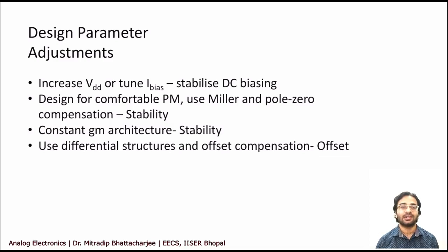Now there are different design parameter adjustments as well. So you have to adjust different design parameters, and adjustments are required. For example, say increase VDD or tune I bias. I have already said the biasing has to be tuned, otherwise you may not stay in the linear domain.